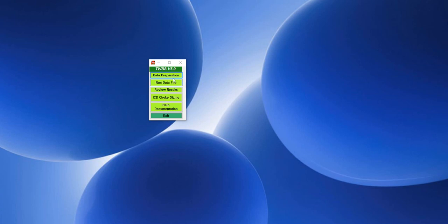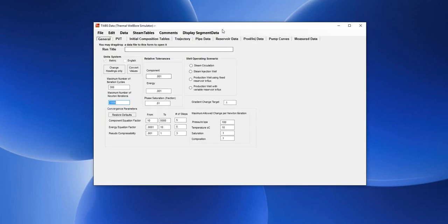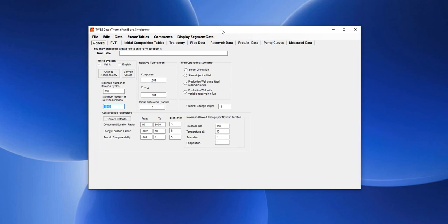Sometimes as we cool down the reservoir, we decrease the steam quality and eventually condense the steam into liquid water. When the reservoir is cold, say at initial startup, that's exactly what happens: the steam coming down the long tubing condenses to liquid and then comes back up the short tubing riser as a liquid column, and it requires additional pressure to lift up the column.